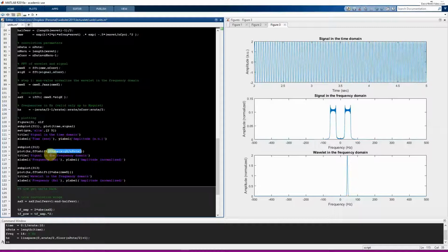So this stuff gets so annoying to do correctly that people often take shortcuts like this, which is, of course, in this case, fine. There is no DC component, or I should say the DC component is 0, and the Nyquist component is 0. So 2 times 0 is still 0. So here it doesn't matter. I just wanted to point out that, even in this lecture where I'm supposed to be telling you how to do it right, I'm still doing it wrong when I don't need to be doing it right.